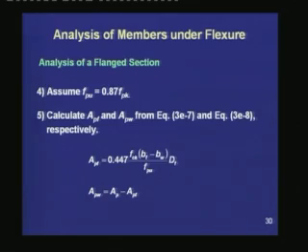If the tension comes out to be smaller than the compression, then the depth of neutral axis has to be reduced. That means, XU is within DF, and we can proceed with the procedure of rectangular section with the breadth of the flange equal to the breadth of the rectangular section.